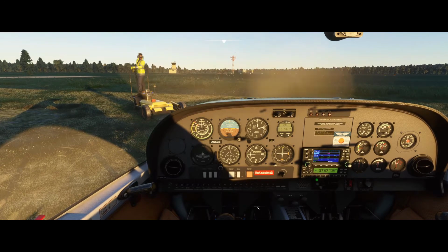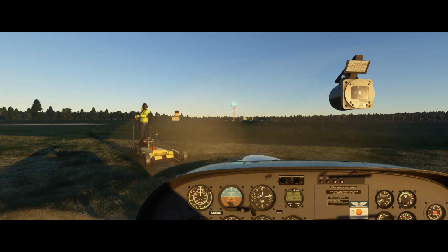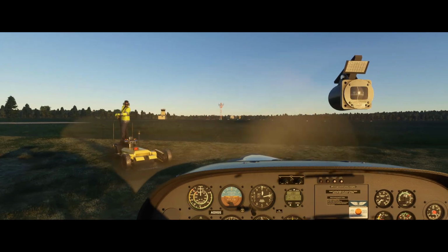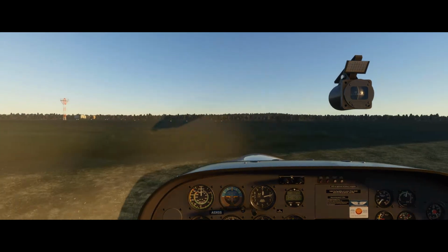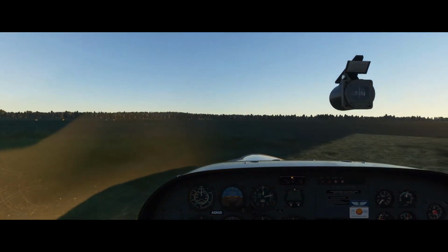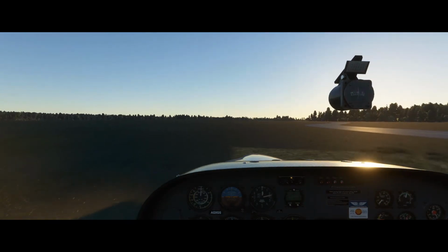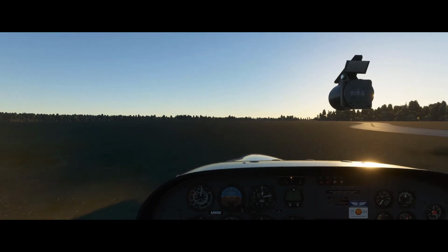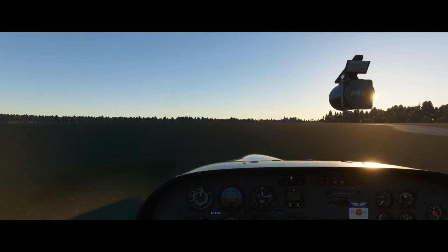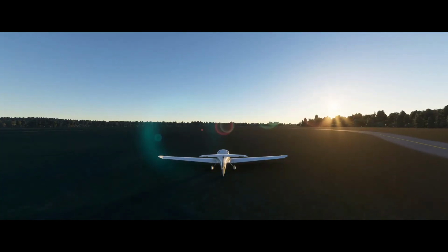The rudder is not connected. The rudder pedals are not connected to the front wheel. So let's just head off on our way, and taxi across the grass. Redhill is a grass aerodrome. We wouldn't go up onto the taxiway over there, and when taxiing, just keep the nose up so that the propeller doesn't hit the ground or doesn't bounce when we're going along.